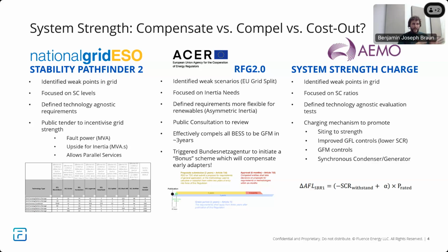What's interesting about that is, contrary to National Grid in the UK or AEMO down in Australia, who were very focused on voltage stability, it's not that the European grid is not focused on voltage stability, but one of the bigger driving factors is actually inertia. They still want to use grid forming controls to get to it. Of course, there are still going to be locations where they need voltage stability, and over the next years, it will only become more and more. But right now, Europe is having more of an inertia issue than a voltage stability issue.